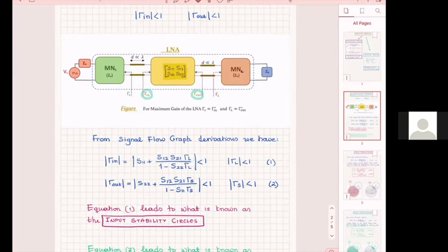Think of your amplifier, which you design, having reflections at the ports. Your incoming signal comes into the amplifier, but your reflections intensify the input signal, and they keep intensifying it over time, then your amplifier goes out of control. It burns out practically, or it's going to start oscillating. Do you know where you see that? You see that in microphones.